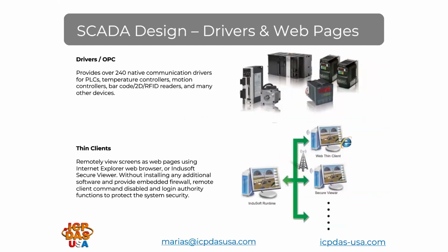InduSoft and AVEVA Edge come with over 300 drivers and have tools that allow you to create your own drivers. One driver that's really useful is the RxTX driver. This driver allows for simple data strings or commands to be sent over to devices and helps break down the response string into several data tags.